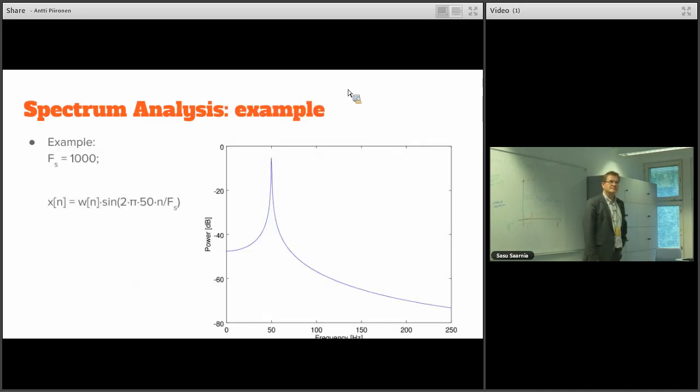And that's the example of a sinusoid signal. Remember, the sampling of a sinusoid or periodic signal is not necessarily periodic anymore. So this is the spectrum with a sampling rate of 1000 samples per second and an exact 50 Hertz signal, calculated in MATLAB kind of system. Well, that's its Octave plot actually.